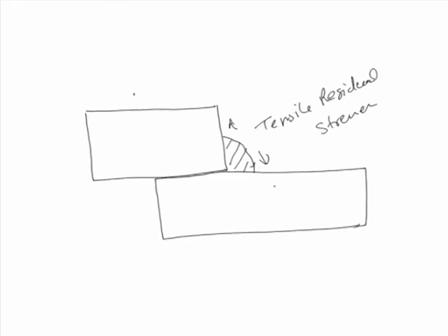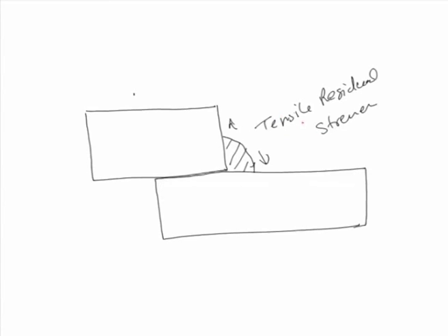So, if the fillet weld is very small in size and deposited on a very thick plate, then due to the differential expansion and contraction of the plates being welded by the application of heat during welding, it will result in heavy tensile residual stresses, and these tensile residual stresses tend to crack the weld from the face or from the toe of the weld.